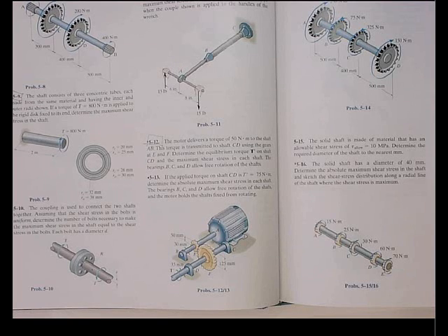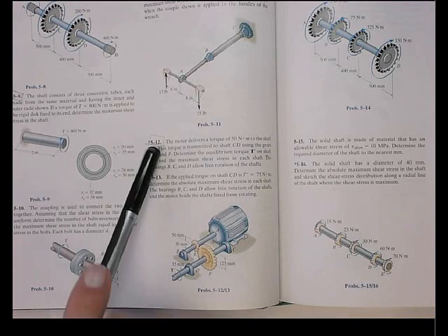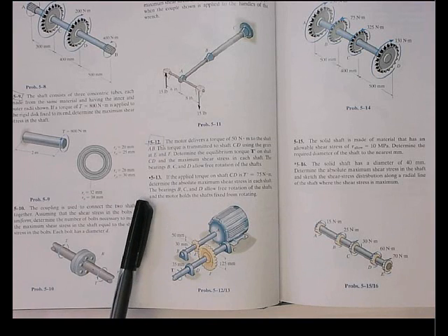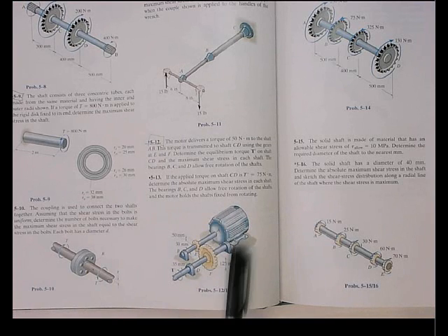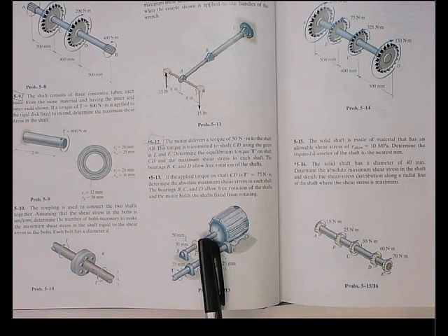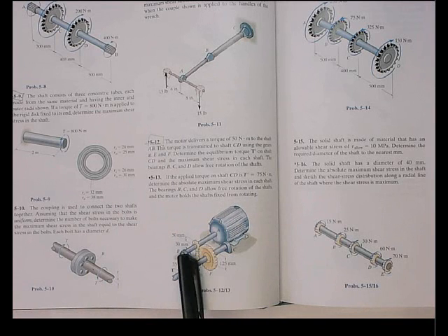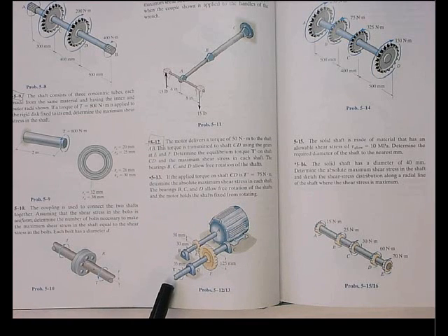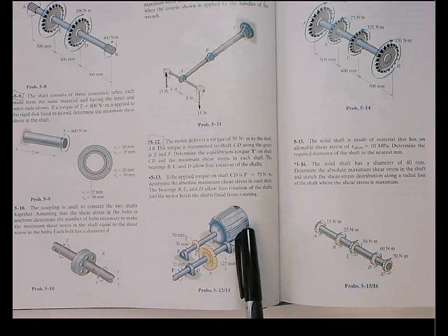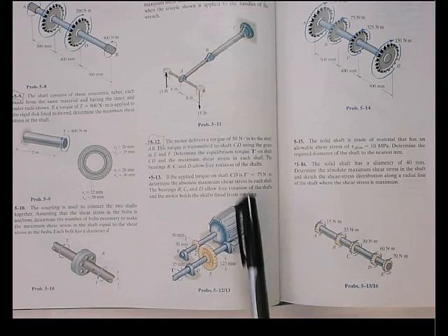Okay, in this video, I'm going to solve 512, and then in the later one I'll do 513. They're both related to the same problem, where you have a motor with an input torque that drives a smaller pinion that then drives a larger gear that's on an output shaft. In 512, they're asking, what's the torque that you would put on the output shaft, like a load, that would equilibrate or balance the input torque of 50 Newton meters.